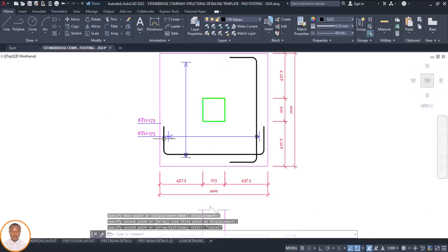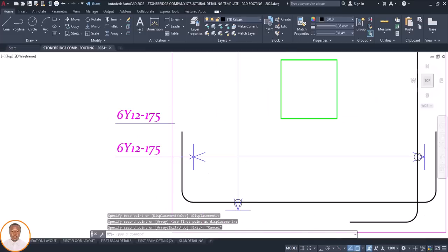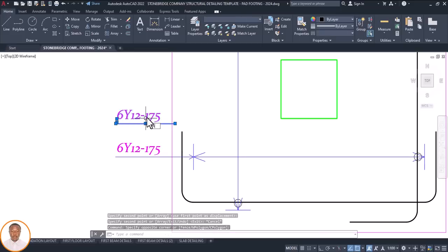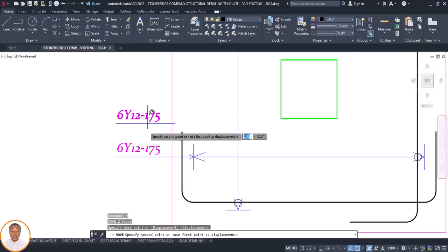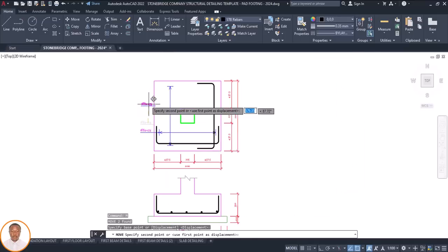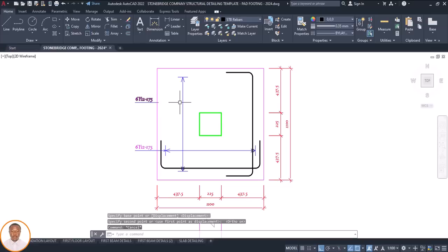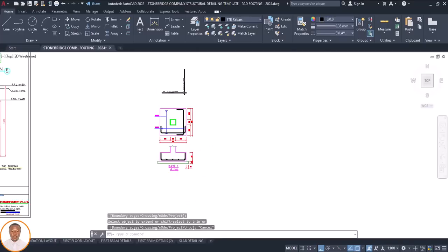Okay. Then that's for this one. Then carry this one. Move this one up. Take this one here. Then CP. No, sorry. M. That's M to move it. I'm taking it up a little, maybe somewhere here. F8 to make it straight. Okay. Then I'll click on this one. Then extend, EX, enter. Then click on this to take it to that side.